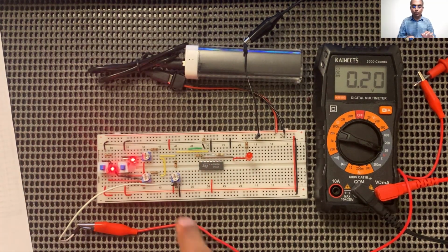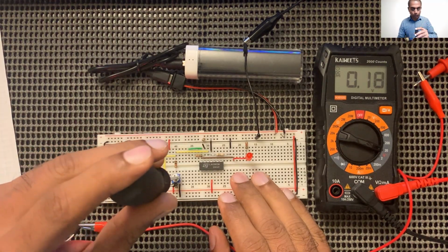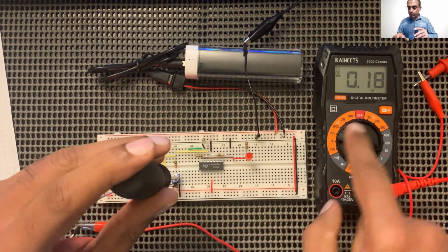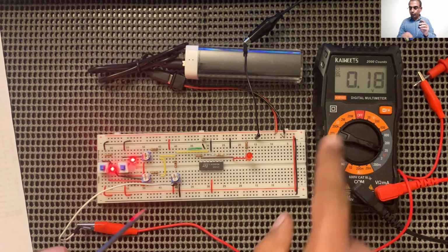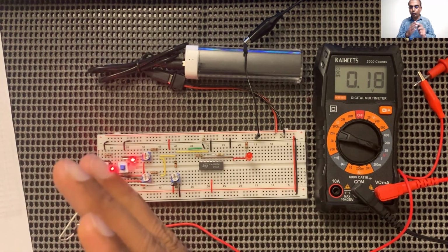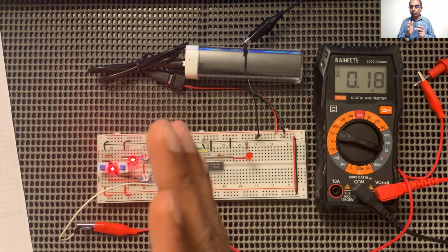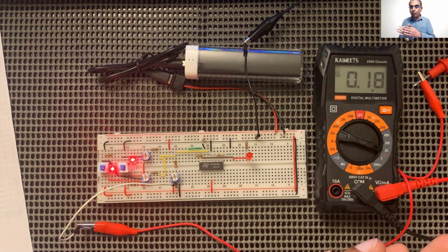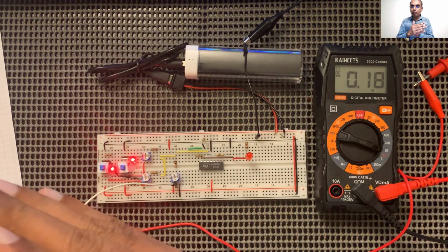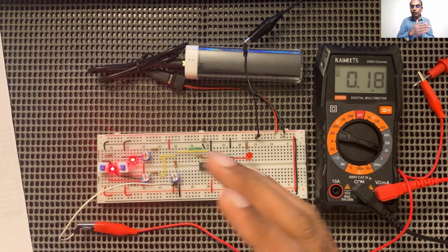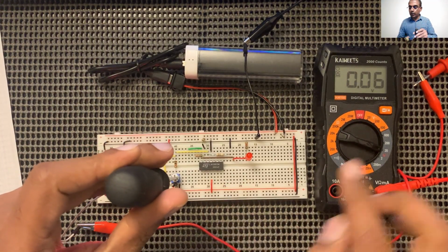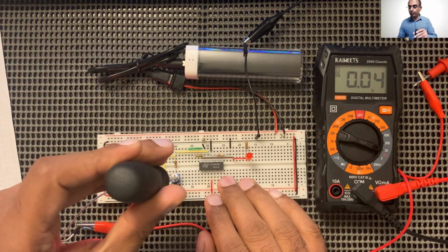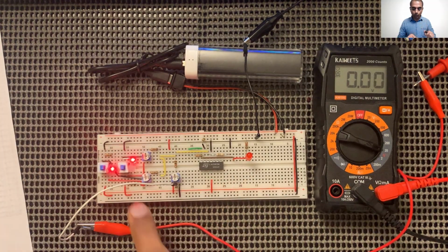I will connect the input terminal of this multimeter to the bias first, and then I will tune the bias to 0. Now you can see that the current bias potentiometer wiper output is at 0.18 volt. When I tune the potentiometer to the right, I'm going closer to 0 voltage. If I tune it to the left, I'm going closer to plus 5 volt. So I'm going to turn it to the right as far as possible until the potentiometer value becomes 0. Okay, now it's 0.